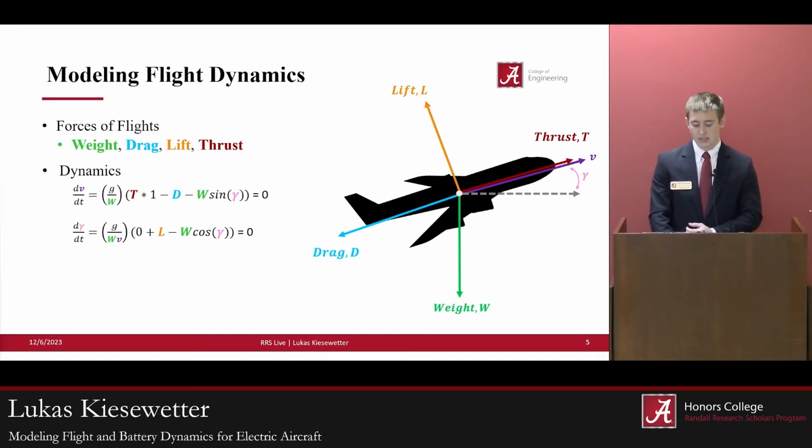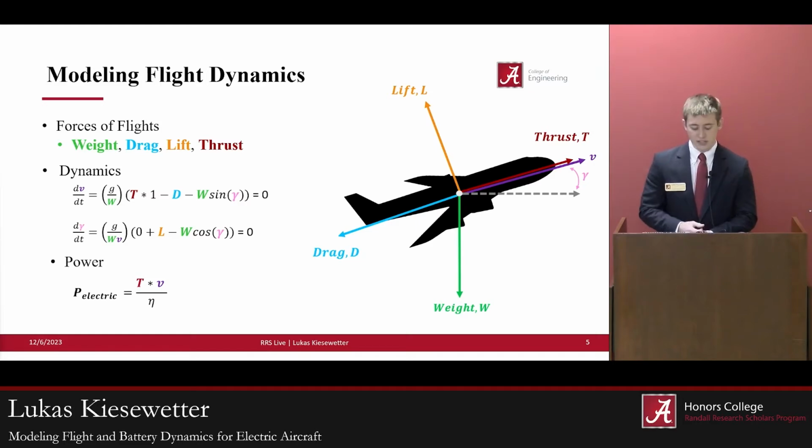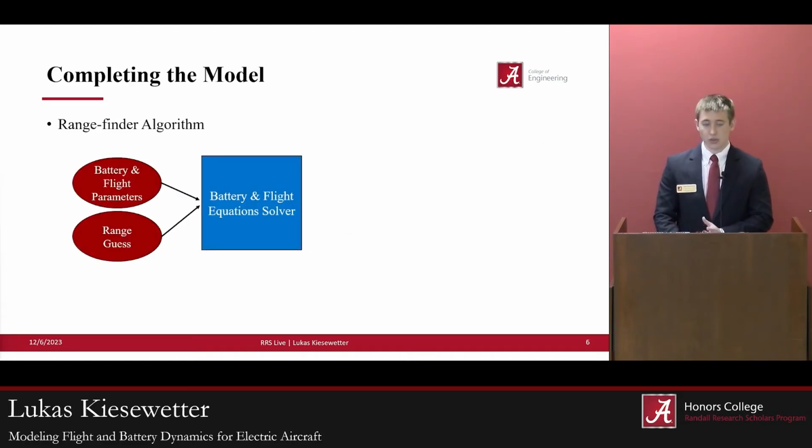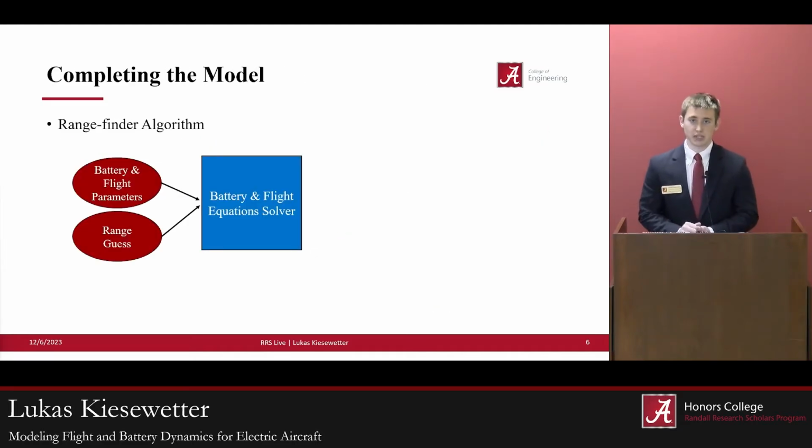The reason we want thrust is this is how we can find the power required that the battery must produce in order for the aircraft to fly. Thrust is multiplied by velocity and divided by some efficiency, eta, and then you can get the battery power. So this successfully links the battery and flight models together, and we can do this all in MATLAB. That is the engineering program we use to simulate all of this.